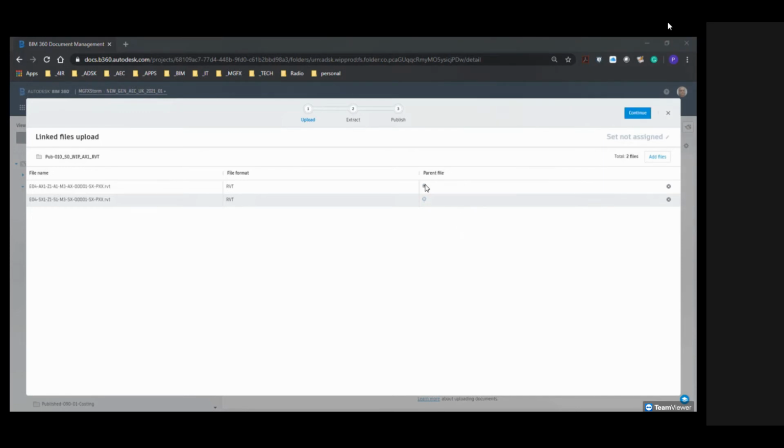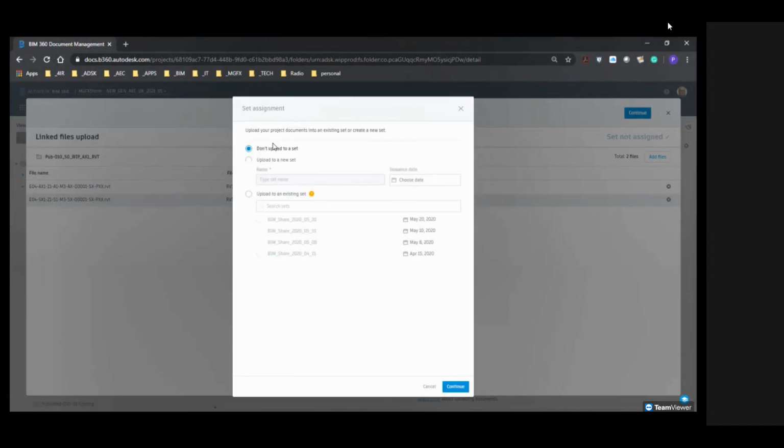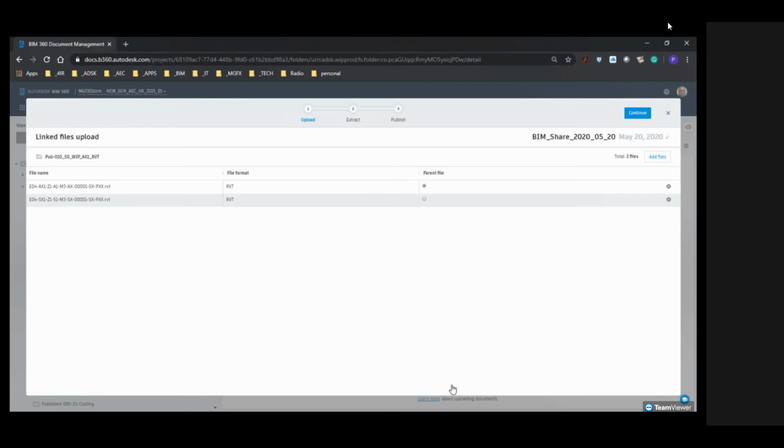Now, I may just mention in the background that I have uploaded DWG files and PDF files and Revit files into the same folder. The files are called the same thing, and BIM 360 doesn't have a problem with that. So if you're after one source of the truth, I would recommend you work according to a BIM protocol. If you work to the BIM protocol, then you would state that if you are using Revit, then you must upload either PDF or Revit files, and the same thing with your AutoCAD files as well.